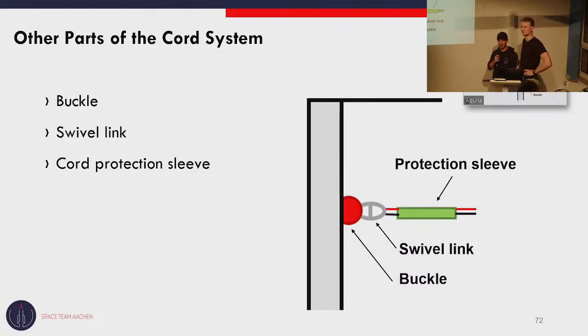We actually have someone working on Carl right here. Maybe he could answer the question better. Yeah, I didn't work on Carl 1 specifically, but I was in the recovery team for Carl 2. So in Carl 1, we actually had a nominal drogue parachute deployment, but what we experienced is that the main parachute was deployed too early, so the main parachute bag was not shut properly, and the main parachute deployed at apogee as well.